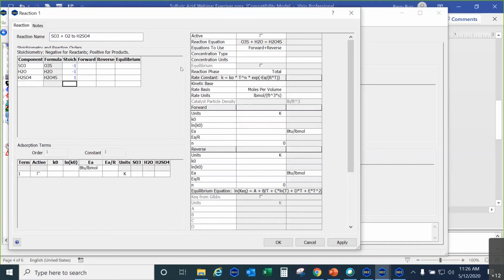And the reaction is only in these distillation columns. If you're going to use a reaction in a distillation column, you have to choose either the liquid or the vapor or the heavy liquid phase, maybe, if it exists. But you can't use the total phase for a reaction in a reactive distillation column.